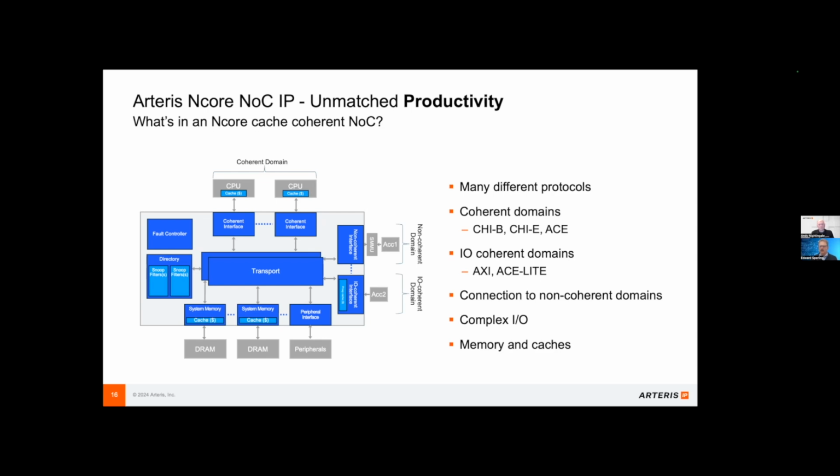This works really well with chiplets too, right? Because now you can say, oh, we can just plug in a chiplet and we can know how to move that data around. Yeah, we can have effectively a coherent NoC on one side of the chiplet and a serial pipe going across, talking to a NoC on the other side of the chiplet. And that data is actually transmitted as if the NoCs are right next to each other. And the integrity of the data can still be maintained by all the mechanisms that you have on either side of the NoC. And that doesn't matter whether it's sitting side by side or going up into a 3D IC or a 2.5D configuration, right?